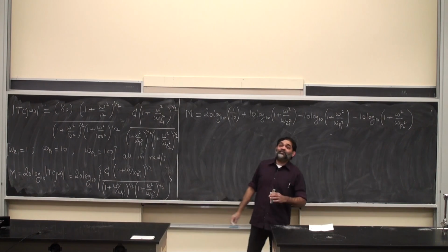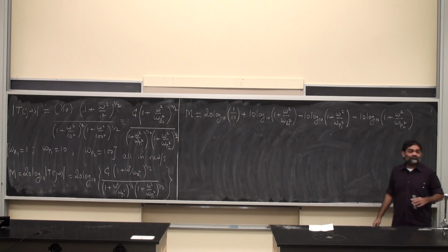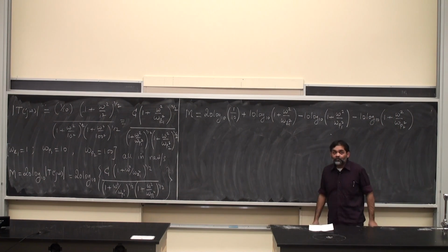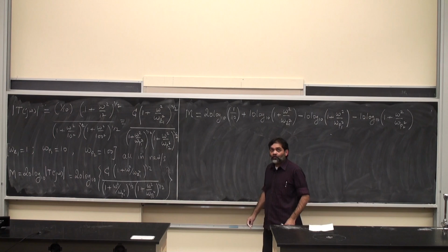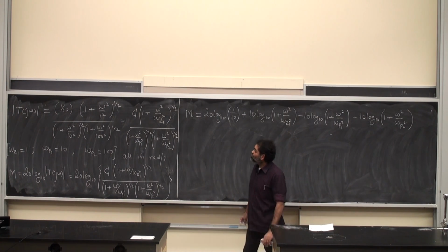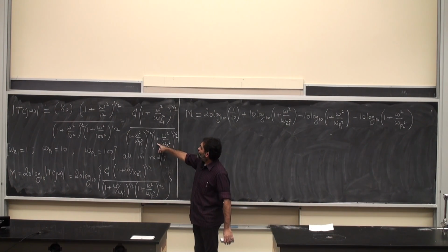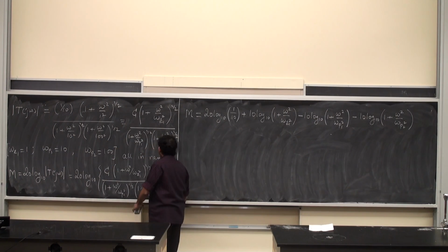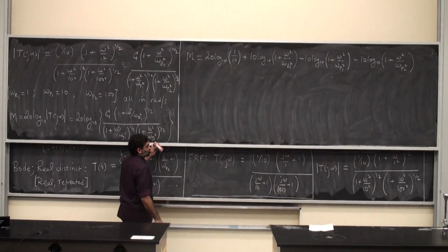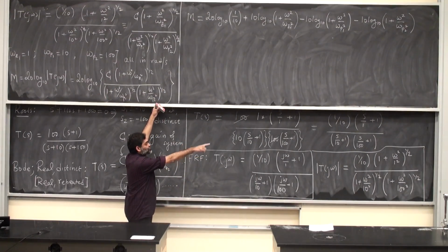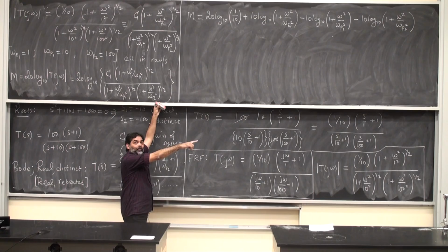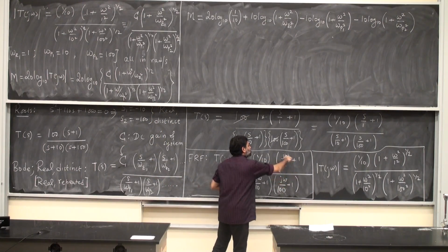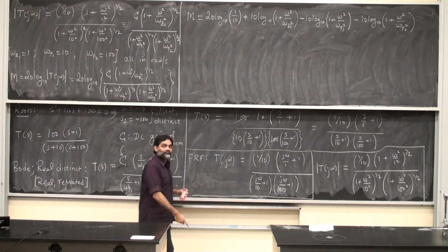All of us on the same page? How did the factor of 20 go? Yes, sir, question. The only part that I was a little bit confused about was how you got the transfer function for the Bode plot in that form, omega squared over 10 squared, the one to the left. Oh, we just did that here. All of these steps. You write that first in the standard form there. And then I have a j omega here. And then I have to take the magnitude of each of these numbers. Okay?